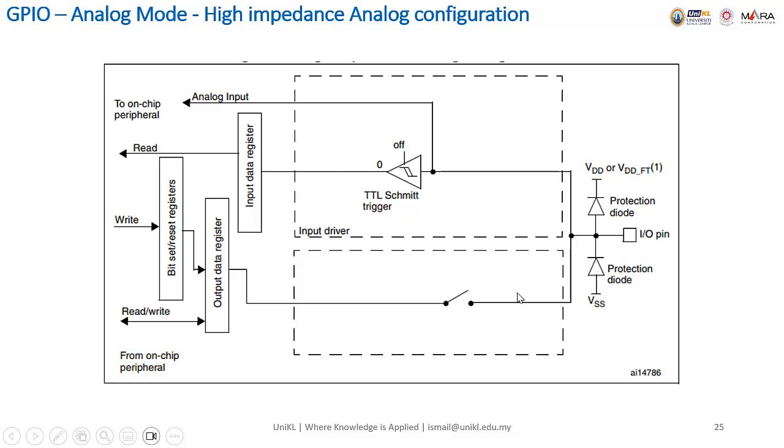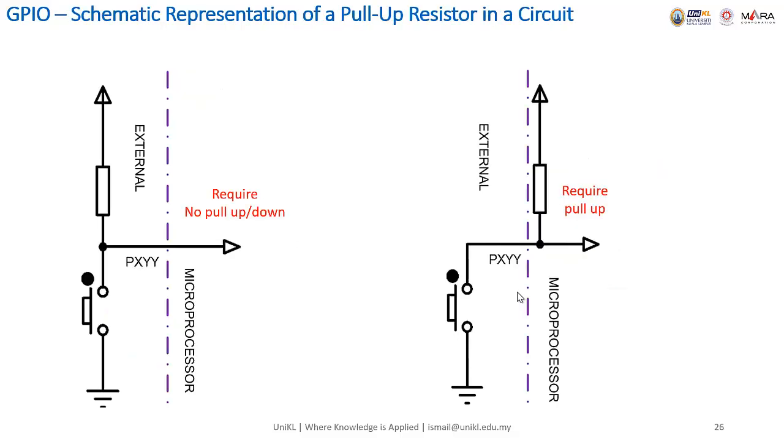Yeah, I forgot to copy the block diagram, the circuit. All right. Basically, we can arrange the push buttons like this, where we have the pull-up resistor pulled to VCC. So by default, this is active low because it is open. When we press, it becomes low, so we call it active low.